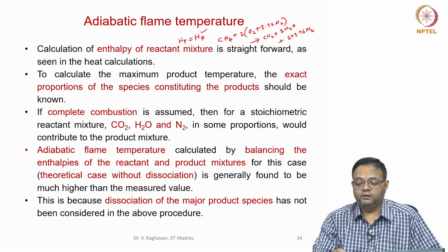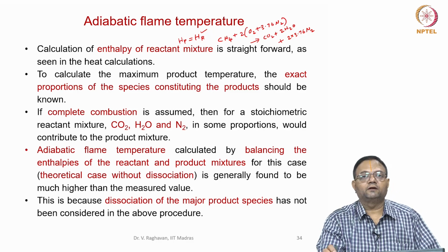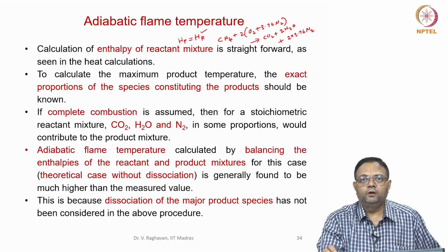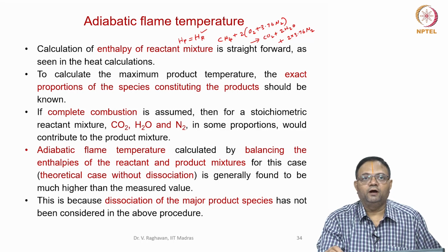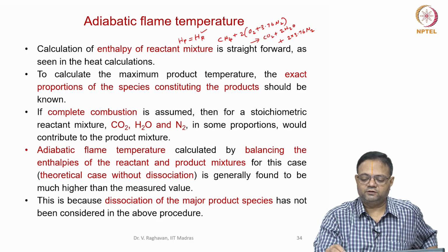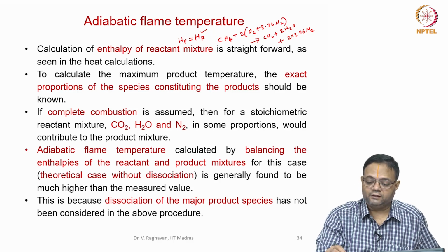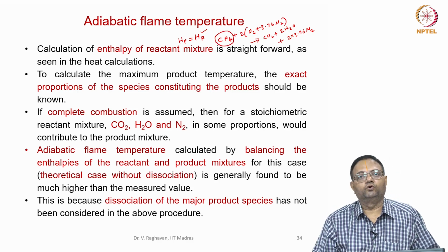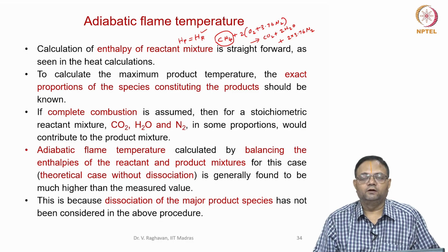On the reactant side, the temperature of the reactants is known to me. HR is nothing but the enthalpy of CH4 plus 2 times enthalpy of O2 plus 2 into 3.76 times enthalpy of N2 at whatever temperature. But if it is at 298 Kelvin, the enthalpy of the reactants will be only the enthalpy of formation of CH4. So often I know that.